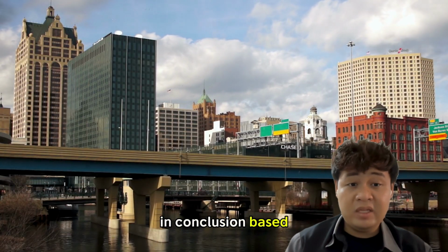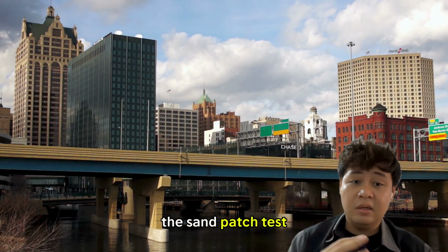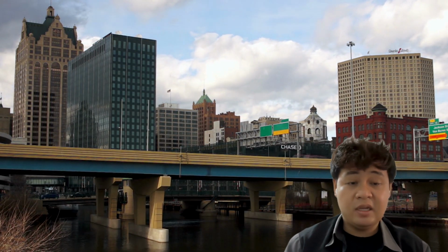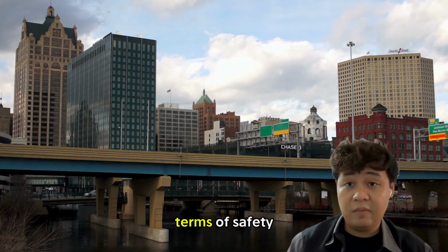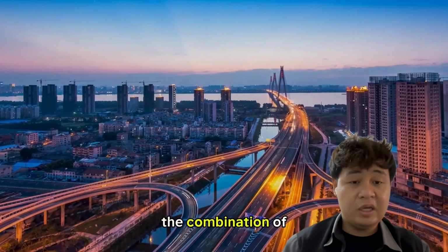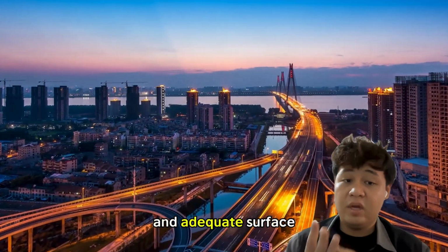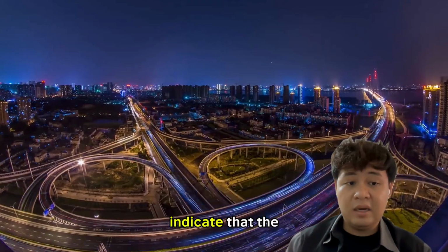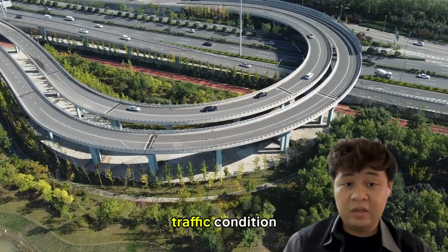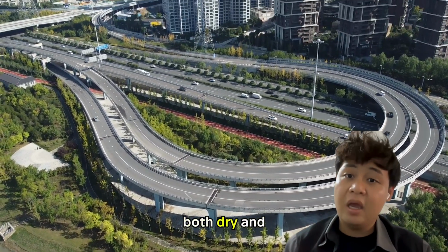In conclusion, based on the surface drainage, skid resistance, and sand patch results, the pavement surface demonstrates satisfactory performance in terms of safety and functionality. The combination of good drainage capacity, high skid resistance, and adequate surface texture indicates that the pavement is suitable for low to medium speed traffic conditions and performs well in both dry and wet conditions.